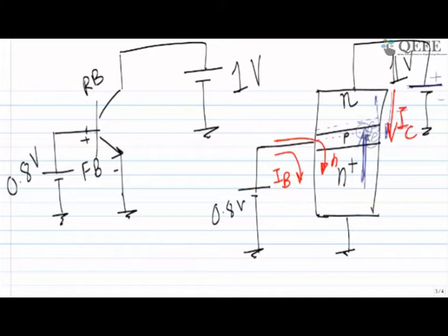What we have pumped was base current, and what we got is collector current. There is a difference between IB and IC, because you put a very small amount of base current, and what you got as collector current is very big because of the heavily doped N plus region, and that decides something called current gain, very popularly known as beta.